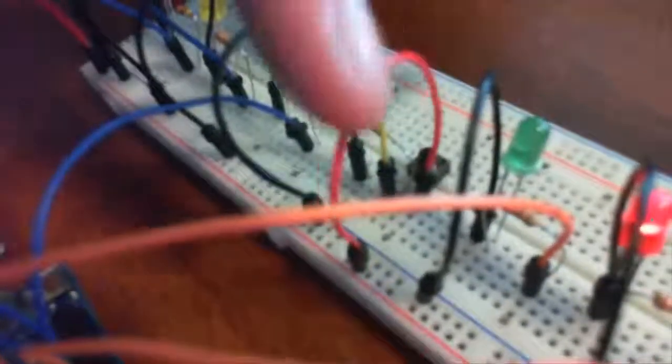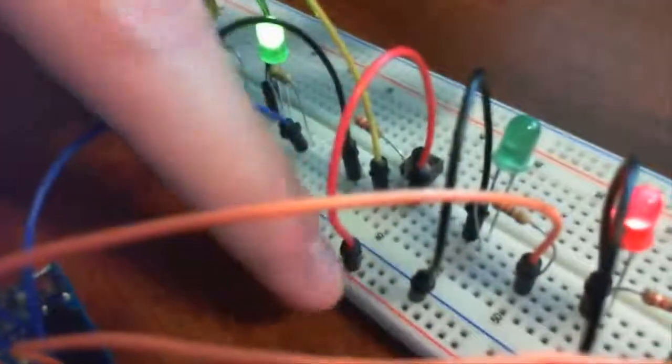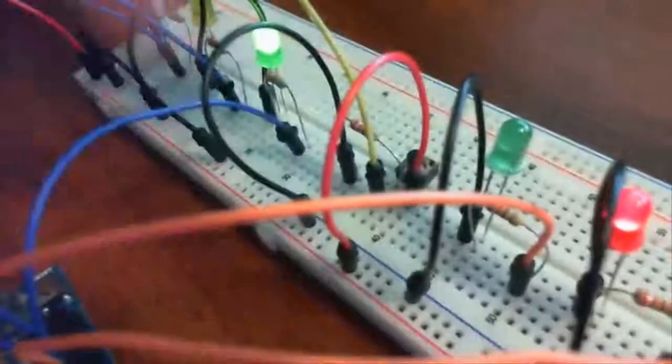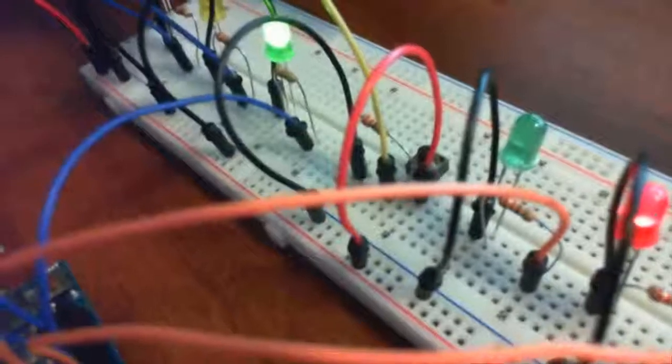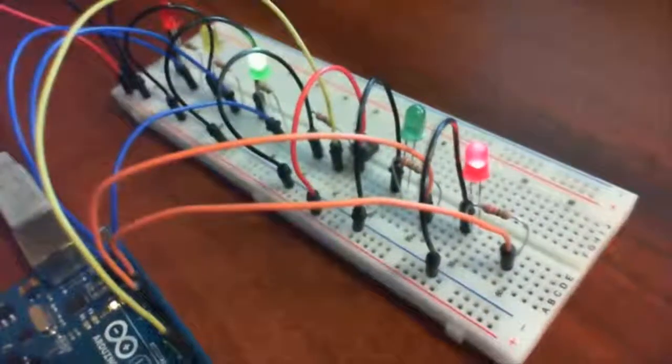Well, everything else like that is the same except for the button right here. You see, the right side of the button, since this is an input, you need an input that goes to the voltage, the 5 volts right there. And then you also have a resistance that goes to the ground, and then you also have the input wire right here. So here's a backup. Right here you can see, I'll show you down.